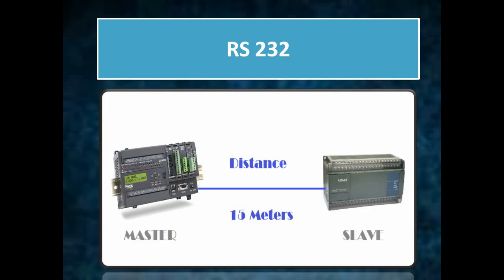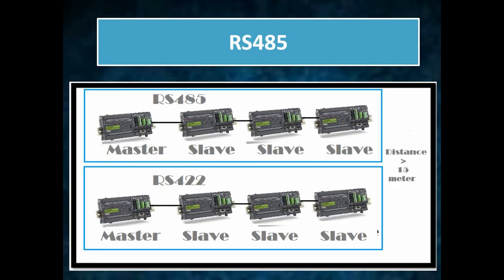You can see, here we have one device with a point-to-point connection. We are going to connect like this, but if we have to connect the devices in an arrangement as shown in the figure, one master and the slaves attached in series to that, then we are gonna use RS485.